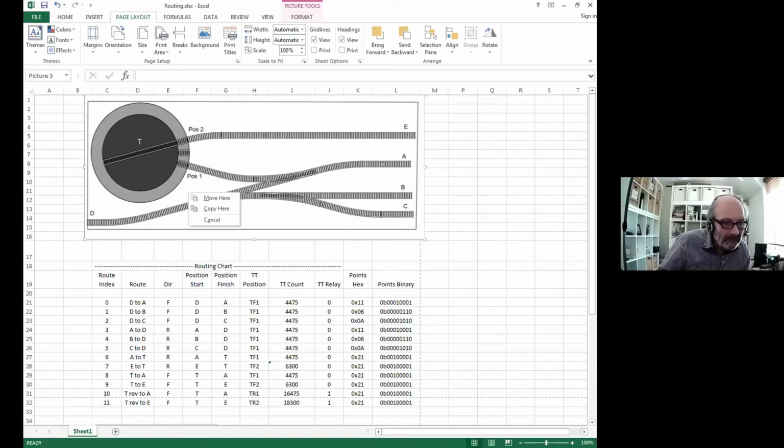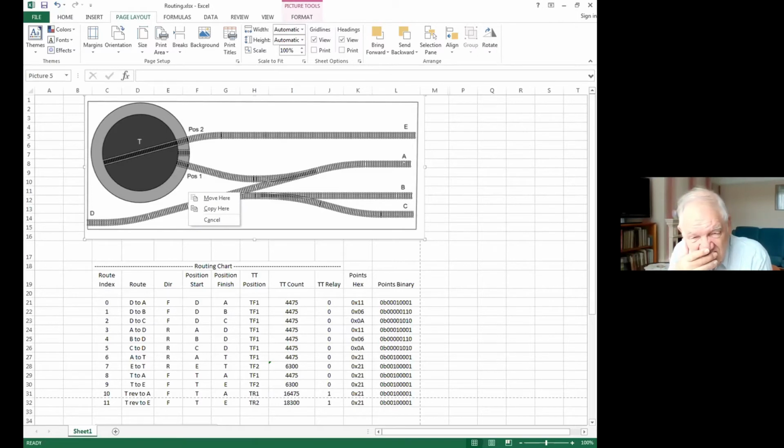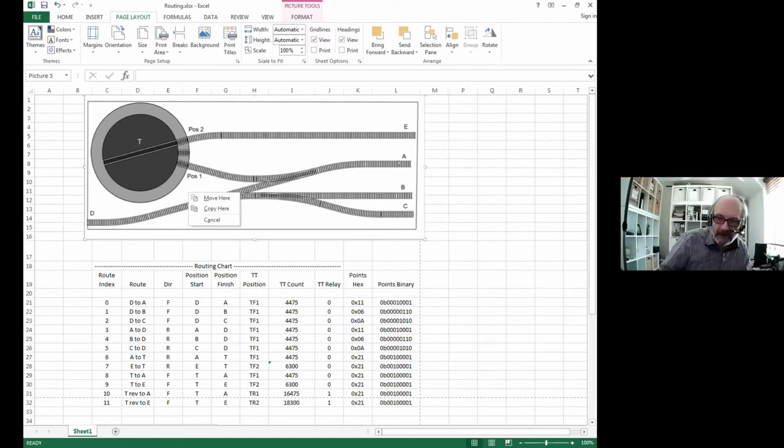And with the end detection, because it's diode isolated, the standard way of doing it, when it hits the area that's protected by the diode, I've got a large value capacitor across there, so when it goes into that area it charges the capacitor, and charging the capacitor passes current through the motor, so it doesn't come to a dead stop, it slows down.